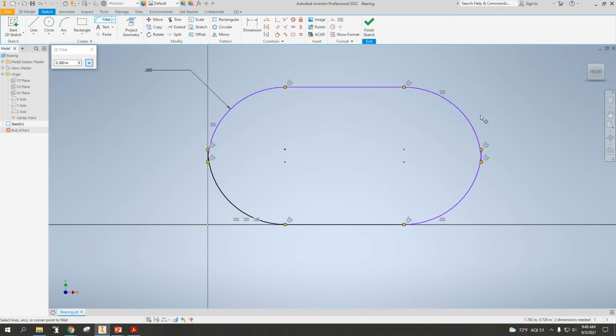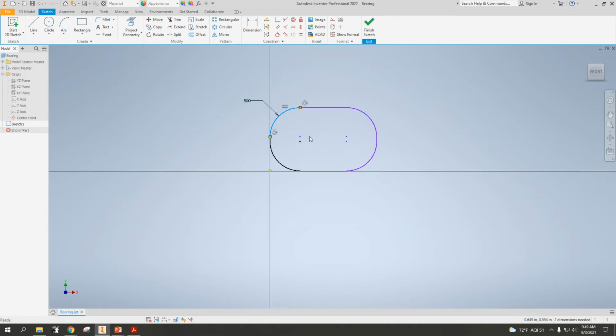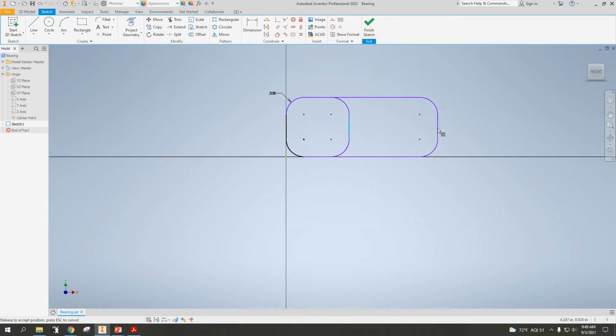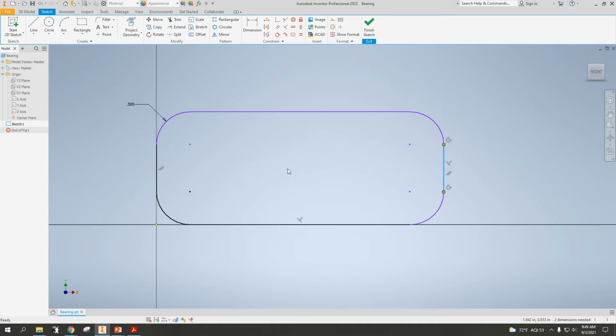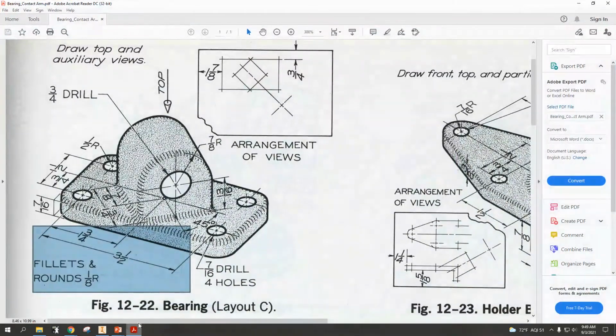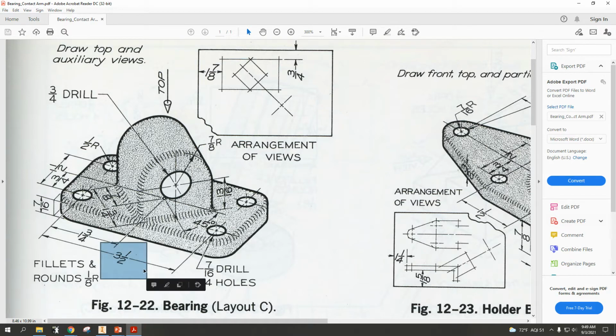Now, I may run into problems here. We'll see shortly because, it looks like it's going to work all right. My sketch was just a little too small. So maybe the object really looks a little bit more like that. And again, you can see that I still have a number of items that are not locked down yet. But that's the basic shape of my base. And so now I can go and put in dimensions to the centers of those radius corners. So I've got 3.5 on the long way and 1 1/2 vertically or depth-wise.